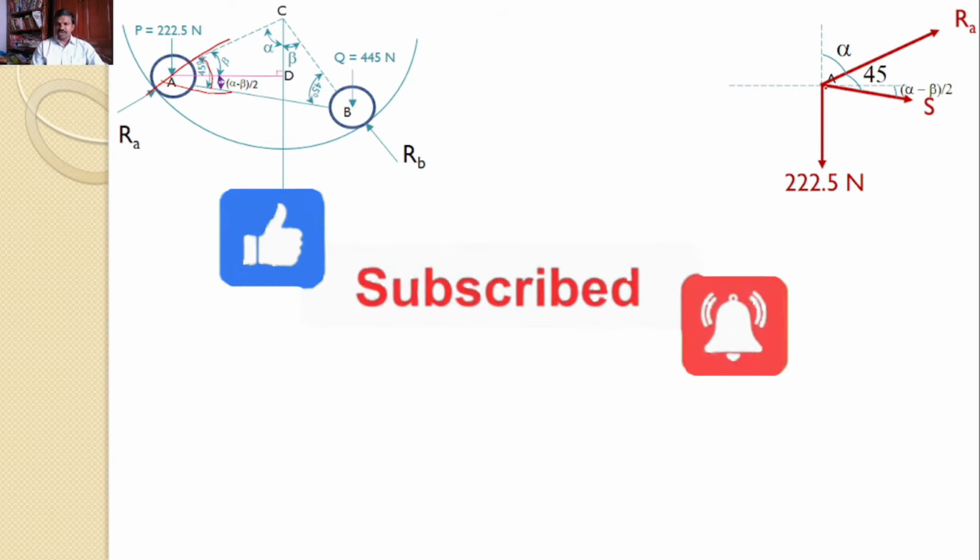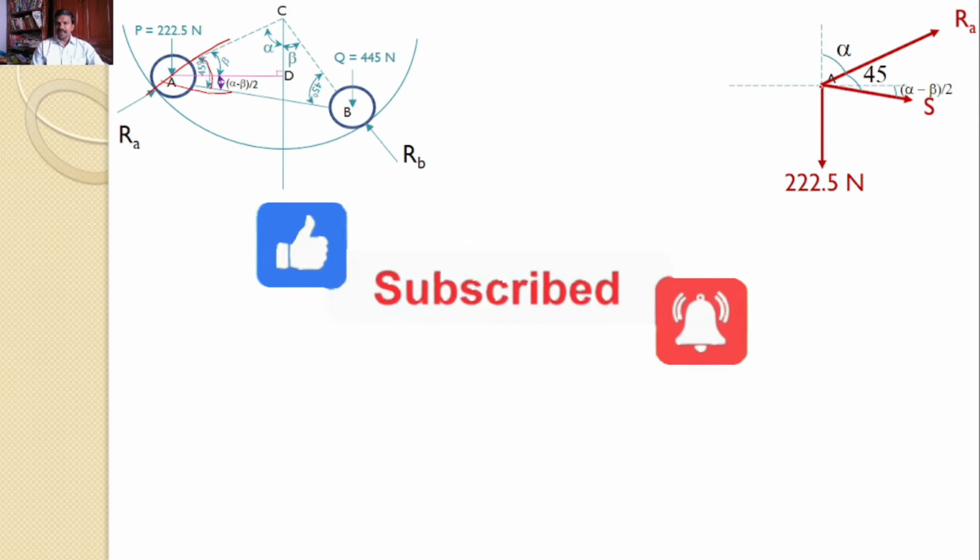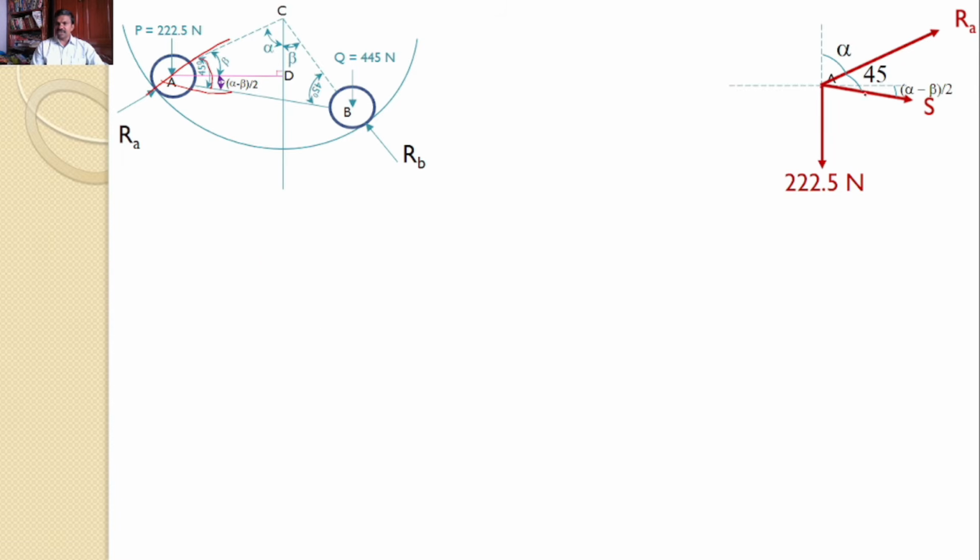Now there are three forces. All three forces are concurrent and all three forces are divergent, and I know all the angles, hence I can apply the sine rule. According to the sine rule, force divided by sine of the angle between the other two forces is constant.